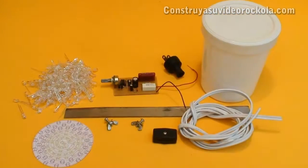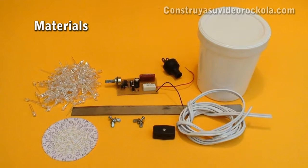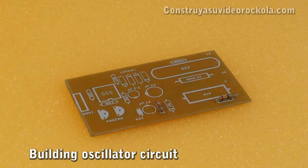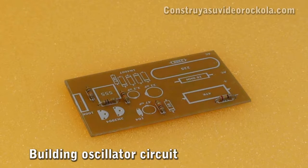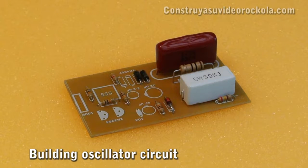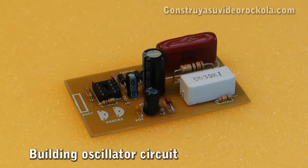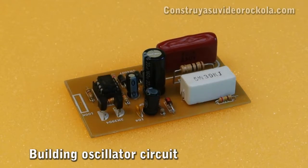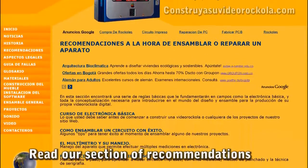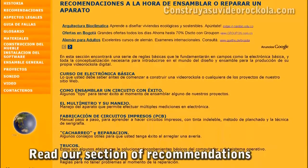Construction. After downloading from our website the PDF file with the list of materials, wiring diagram, and the PCB, we must begin to build the oscillator card. You should put in all the components using the mask as a guide and review the components thoroughly before soldering. If you have no experience in assembling an electronic project, be sure to read our recommendations section.